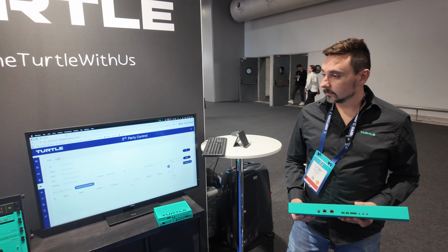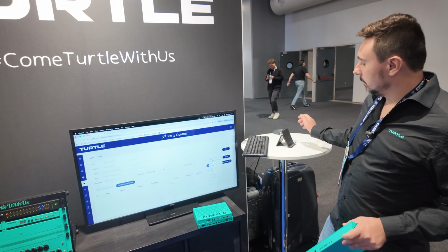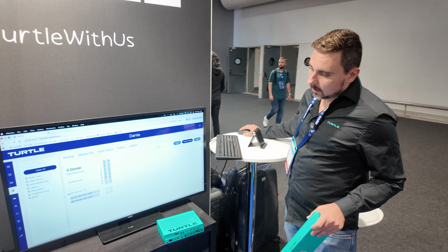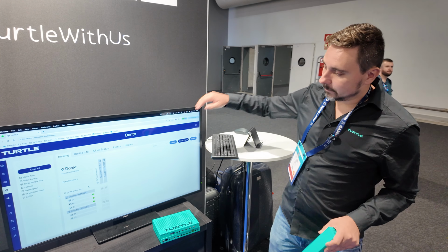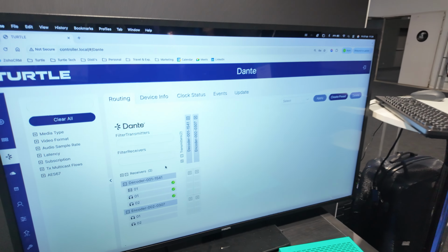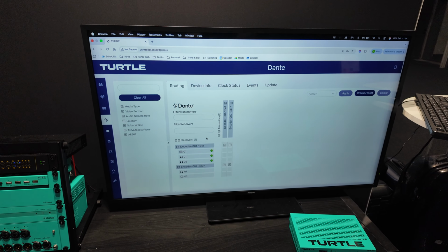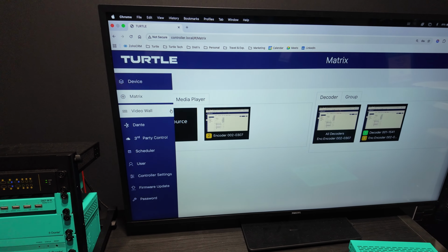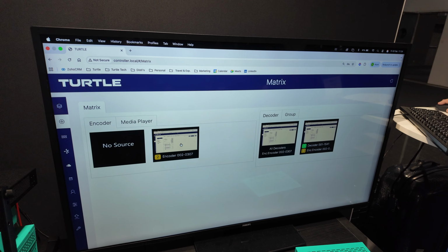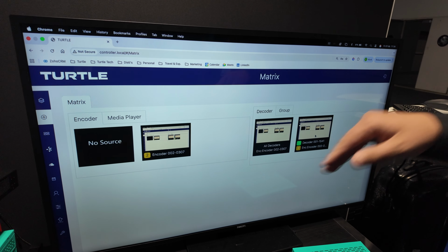Is this the same interface you're using to control AV-A also? Correct, yeah. So as you can see, if you go back to Dante Controller, in here we have got two audio channels and there's a video channel directly here. So it all pops up in Dante Controller and seamlessly work with Dante Audio. Video streams also to see it? Yeah, absolutely. So there's a visual matrix here as well. So these are live video previews. You can also do a drag and drop routing. So I can simply just drag and drop source to the destination.